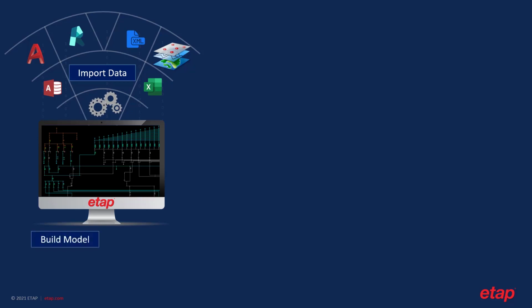You can also build the model or the single line diagram using the templates that we have provided or templates that you may have created over the past few projects. You can utilize auto build to quickly build the one-line diagram, and you can also utilize the standard graphical drag and drop and connect method to build the single line diagram. So any combination of manual, templatized, or import functions can be used to build the single line diagram.